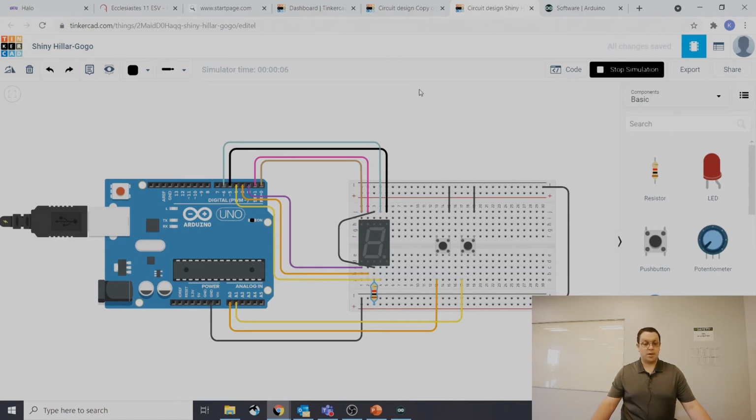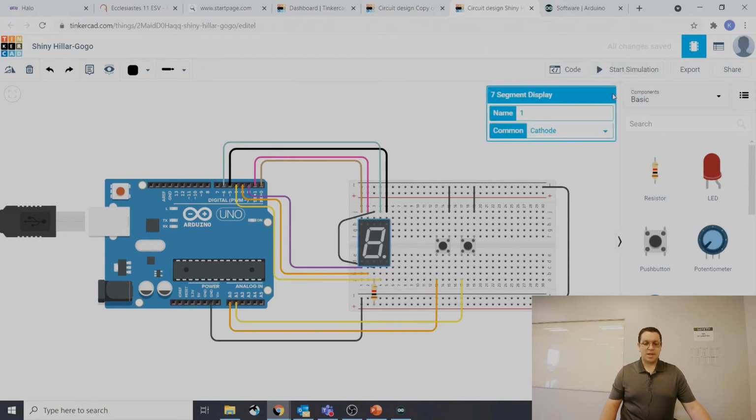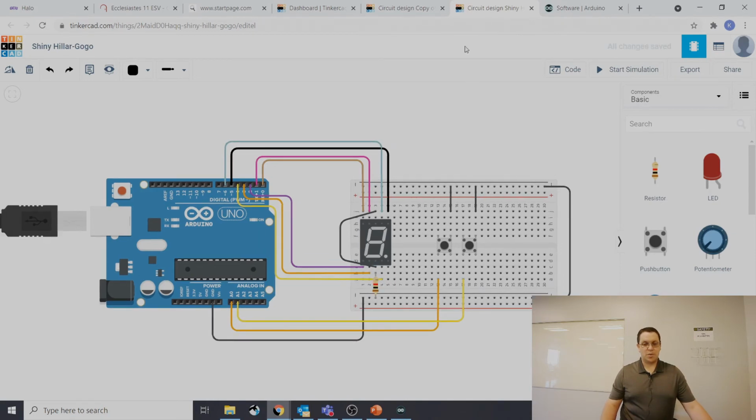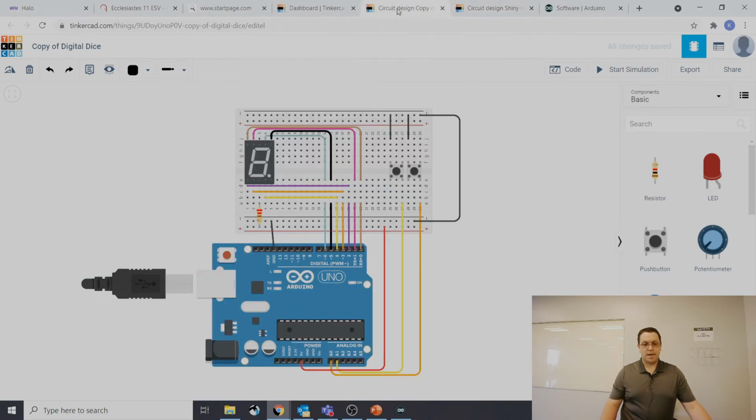And then they're going to go, well, I'm pretty sure it's a code problem, but I don't know why the display isn't lighting up. And then you do some research, and then you figure out, well, this is actually a different type. So we have to select the cathode type display. That means these common ports actually have to be connected to a negative.